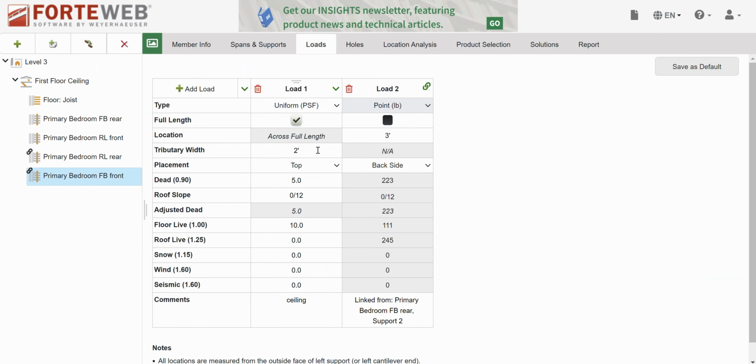I don't have this point load anymore. What I do have is this point load. So let's see how far that's in here. Remember, reading the plan starts reading from the right side of the sheet, looking this way. This is the left side of the beam. So about 3 feet in is this beam. So we'll go and link. This is right, left, front. I think it is, yeah, right, left, front, because there's the hanger. All right, reaction 1, 3 feet in. Placement on the front side, transfer.